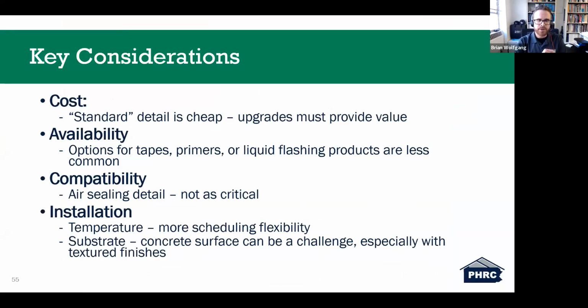Traditionally, the way that we provide some continuity in our air barrier at our framing to foundation detail is through a foam gasket, a sill sealer type product. There are a variety of them out there. You can have more complex gaskets out there too that are a little bit more robust. We've seen more of a push, especially for installations such as modular, for example, where that's one of the more critical details on the site installation of that home, where air leakage can be a problem.